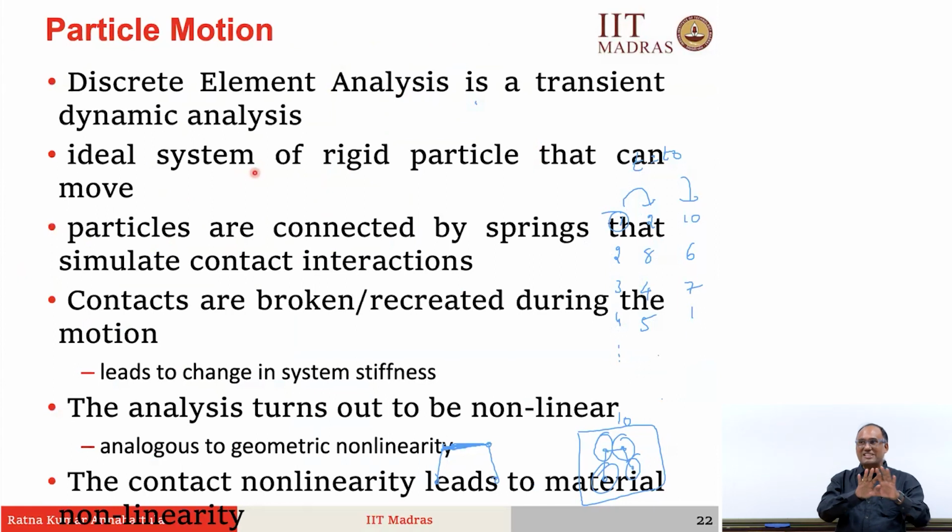Although, you understood the basic algorithm of discrete element method, right. So, we are actually looking at each and every particle, identifying what is the force experienced by each and every particle, and then that force will be used to compute the acceleration and integrate acceleration to get the velocity and positions. The calculation of this force that is acting on each particle can be done in different ways. That means the position update. If you take the hard sphere model, then there is no interpenetration, then you will simply use exchange of momentum, right, and then calculate the positions of the particles.